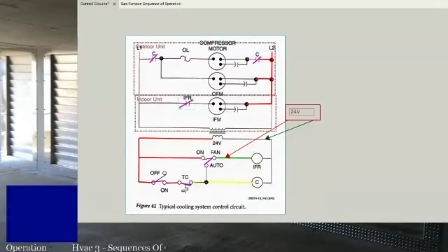Think about, okay, if my compressor outdoors running and my outdoor fan motor's running, I already know in my sequence of operations that I must have 24 volts, that it must be going through the thermostat, that thermostat must be sending power to that yellow wire to the outdoor contactor. But I go and I see that the indoor fan is not running. So at that point, I don't have to check all that other stuff, right?